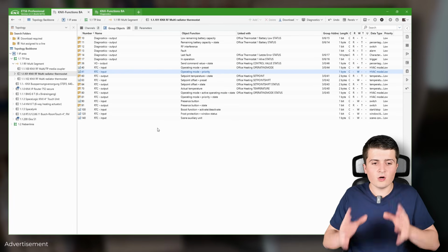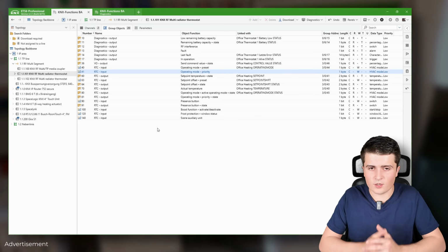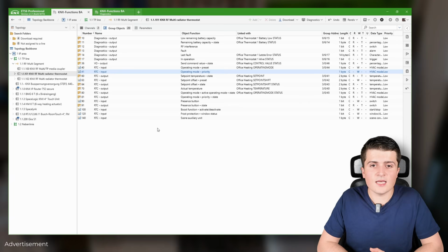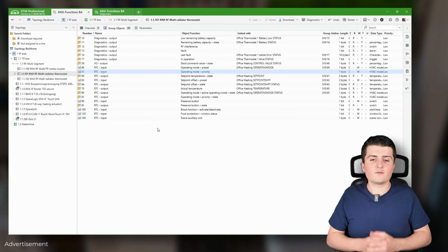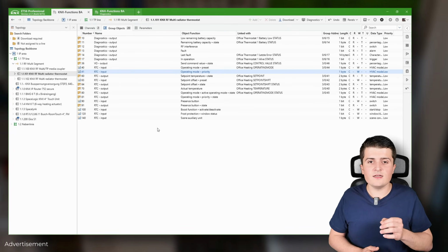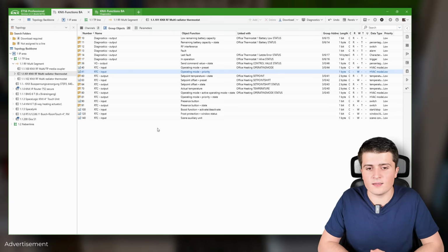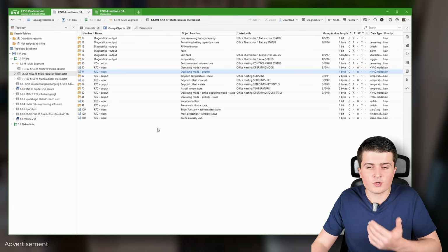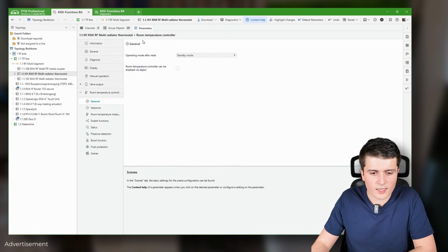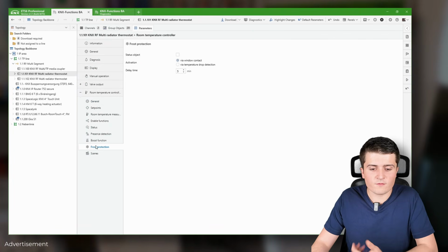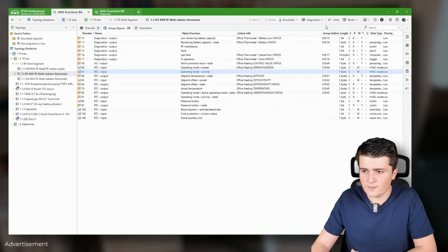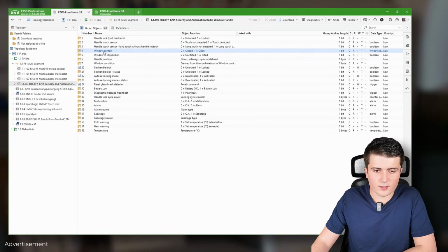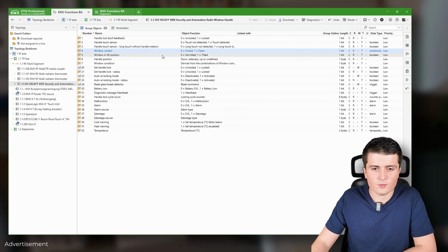And even though we only used ISE devices for KNX RF Multi in this video, there are still other devices available. For example, from the company BSS, there is a KNX RF Multi window handle that you can use. And this is definitely a perfect combination with the radiator thermostat. So I could go into the parameters, enable the frost protection via the window contact, and then I have added the window handle into my installation. Here you can see the window contact group object.